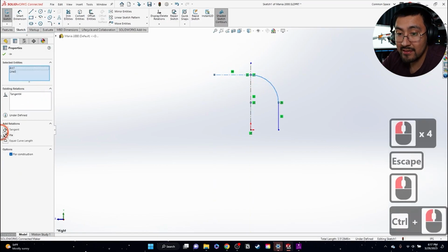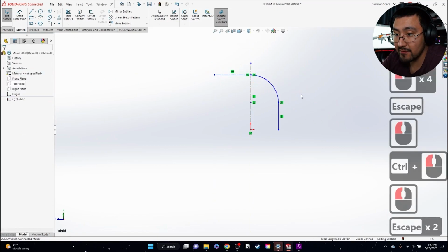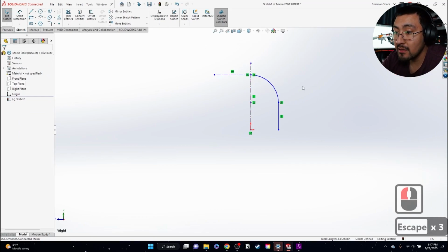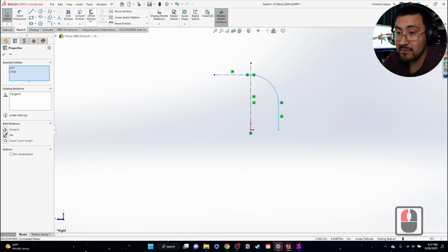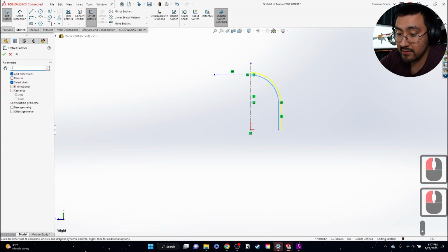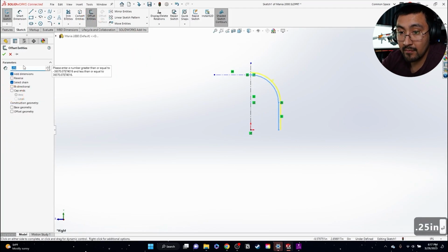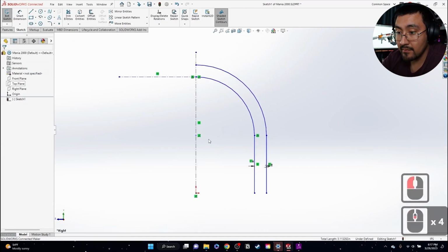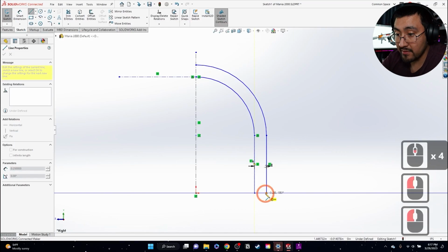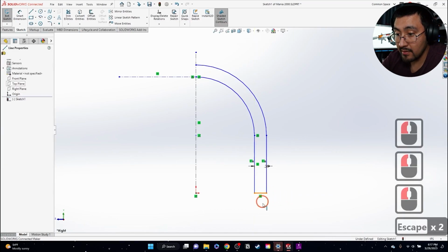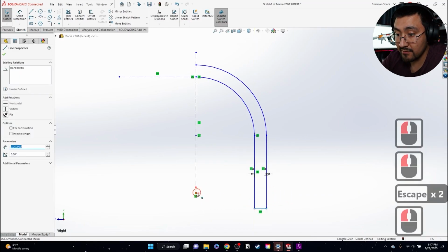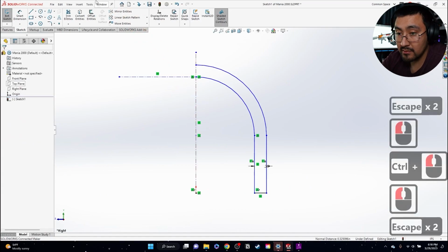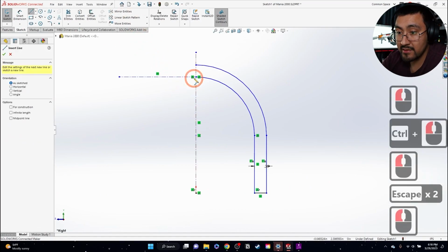I like adding these here just to make sure I get full tangency, so that when it revolves, it's a nice sphere on top. And then this is actually going to be offset 1/4 inch. Oops. This caps off the bottom. Let's make sure this is tied to the floor. Let's cap here.